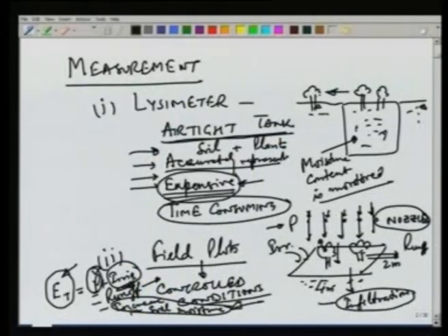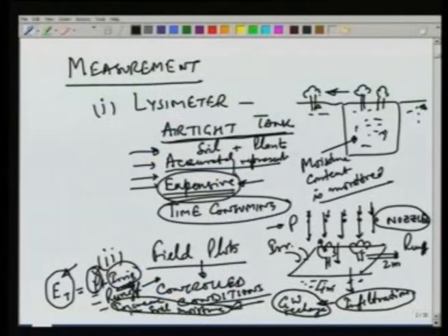There is one more component which is typically used in this equation, as I have shown this infiltration, or we can say that this is the water loss to groundwater or groundwater recharge. So, out of this infiltration, part of it will be retained in the soil, that will increase the soil moisture, part of it will go down and recharge the groundwater. This part typically is very difficult to estimate, and that is why I have not shown it here.